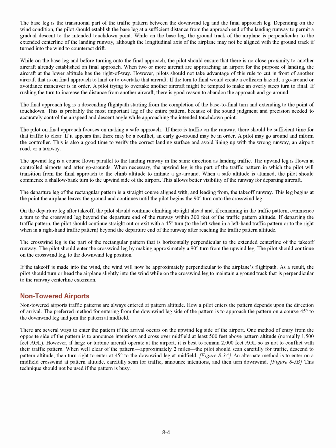If the turn to final would create a collision hazard, a go-around or avoidance maneuver is in order. A pilot trying to overtake another aircraft might be tempted to make an overly steep turn to final. If rushing the turn to increase the distance from another aircraft, there is good reason to abandon the approach and go around. The final approach leg is a descending flight path starting from the completion of the base to final turn and extending to the point of touchdown.